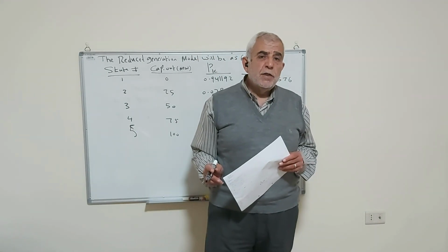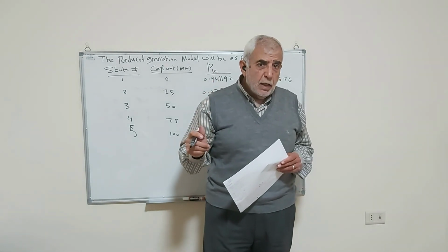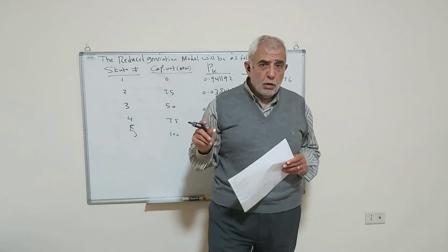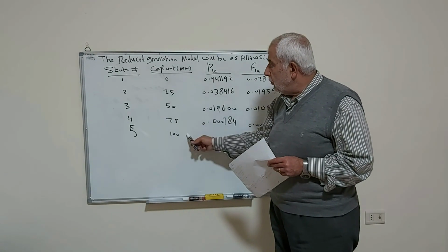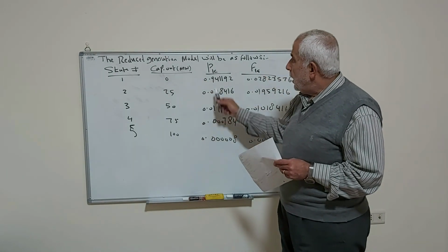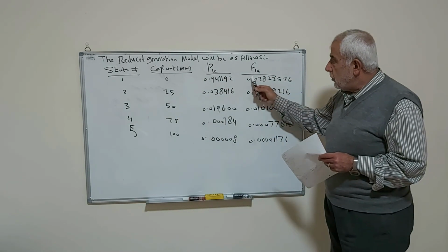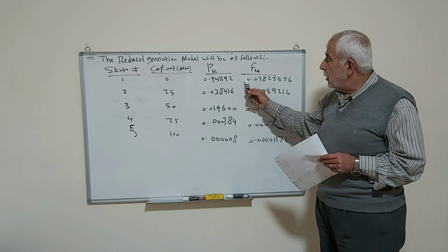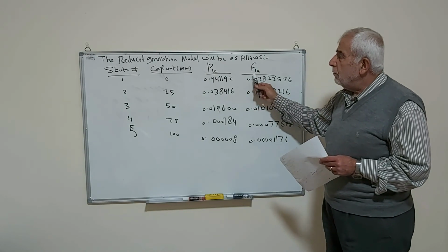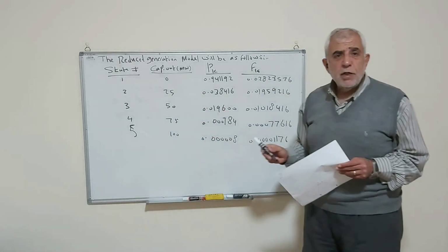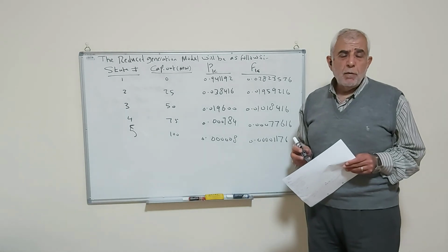We have found the generation model, actual states, emergent states, and the so-called frequency column. It consists of the state number, the capacity out, and we can also calculate the capacity in, and the individual frequency for each state. Once again, frequency means the frequency of occurrence per day for a given capacity outage. Next lecture, we are going to talk about how we can calculate the cumulative frequency and cumulative probability. Thank you very much.